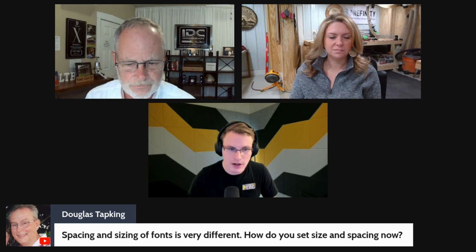Our next one comes from Douglas Tap King. He says spacing and sizing of fonts is very different. How do you set size and spacing now? Before, it was its own tool that we would use. Now it's all in the one text tool. So now when you draw text and move your cursor to the 2D view on the screen, you can click in between the letters to change the spacing. So it's all built in one. Can you show a quick demo of that? Yep.